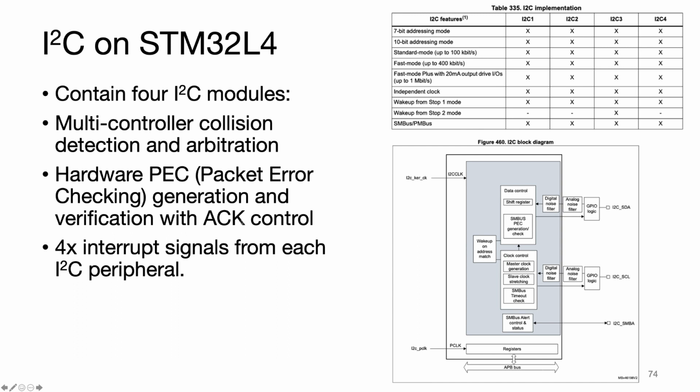It has hardware packet error correction checking, which is nice in the sense that it automatically checks and generates its own ACK control, so you don't have to do that. It also has 4 interrupts because there's 4 modules, therefore there's an interrupt or an IRQ signal for each one of the modules. All right,